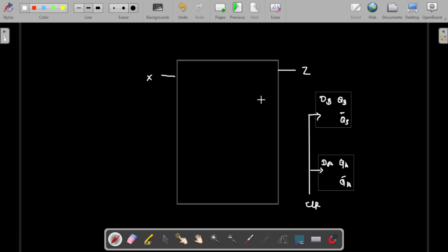So now let us first define our z. We know the equation for z, which is z equal to qb bar qa bar x plus qa x bar. So now let's draw this one. Let us assume that we have qb bar readily available, which means we need to couple it back here, which I will do later. So qa bar and the x input, so these 3 are given to an AND gate, a 3 input AND gate, and that needs to be added through an OR.